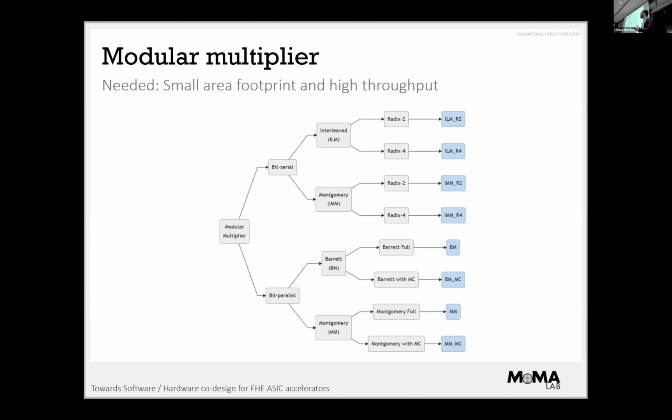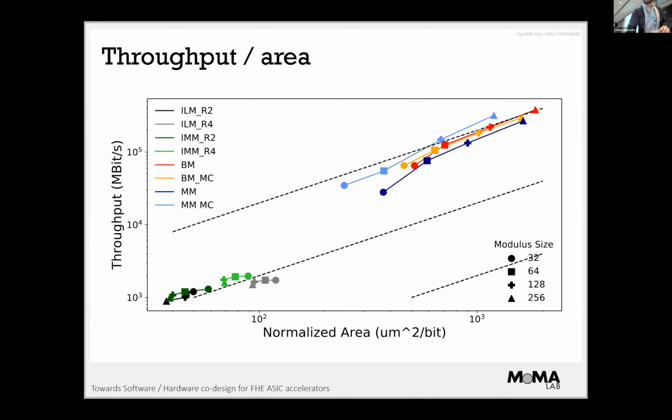And doing that, you can actually reduce the hardware area a lot. So if you constrain the type of the modulus you're employing, then you have a lot of area reduction. However, now you don't have a generic multiplier anymore. But if you only use it for FHE, what do you care, right? You do FHE computation, you can do the modulus constraint. But we explore it a bit differently from the regular ones because you may want the regular ones to be in place too.